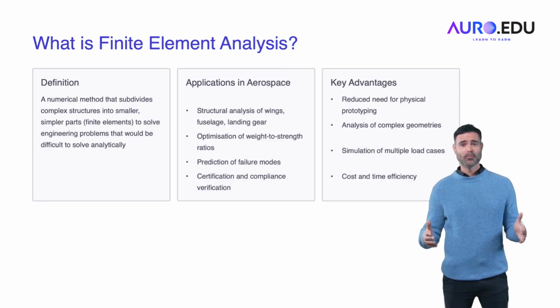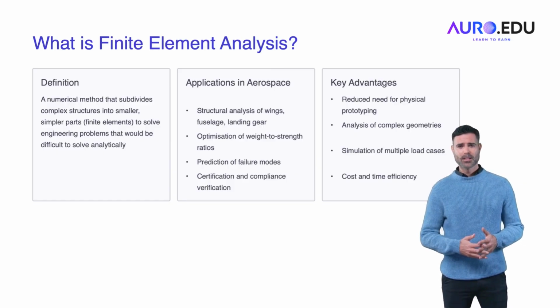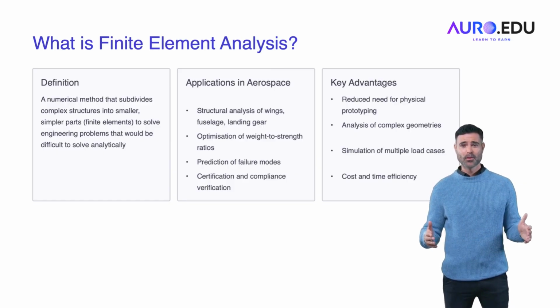FEA also helps predict failure modes, such as cracking, fatigue, and buckling, which is essential for the safety certification of aircraft components. Certification and compliance verification are key in ensuring that all components meet industry standards and regulations, like those set by FAR CS25 for large aircraft. Without FEA, physical testing would be required for every design iteration, making it both time-consuming and expensive, especially for complex structures.